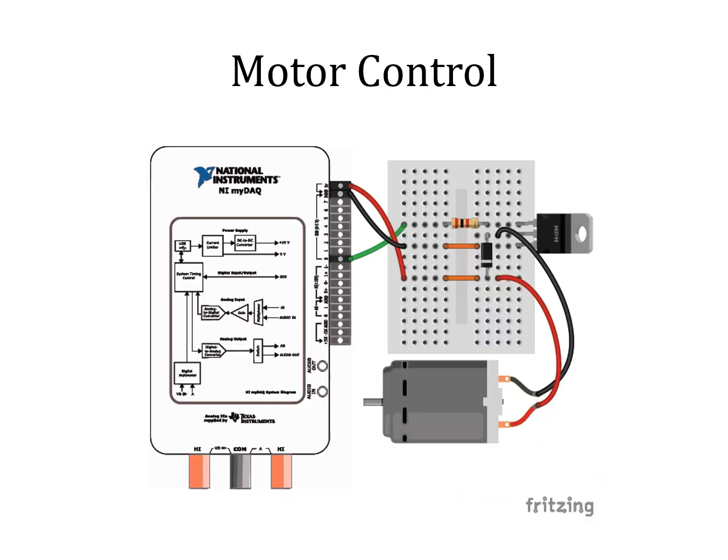There is a very small application, that is, you can also have motor control without any LabVIEW. You can have motor control and you can directly provide an analog signal, and using this you can directly control the motor. So it means by connecting a potentiometer, if I have a potentiometer I can connect that input here, and using that change in voltage we can control the speed of the motor. You can also connect this through USB to any PC, and using LabVIEW we can also control the speed and direction of this motor.